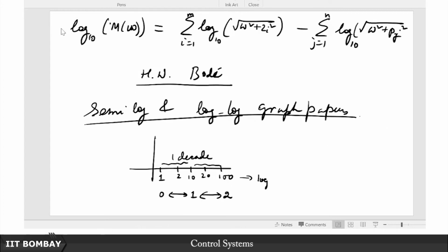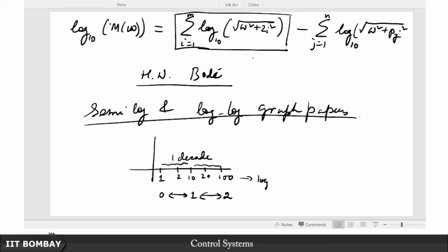So what I am saying by that is, for example here, you add together all the magnitude functions after passing them through the logarithm, all the magnitude functions of the blocks in the numerator, add together all the magnitude functions after passing them through log in the denominator, and take their difference. But what do you do about products and quotients in terms of arguments?